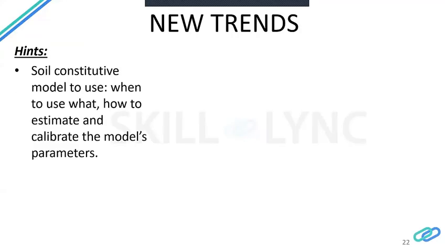Another aspect when dealing with finite element modeling is the soil constitutive model, what type of soil constitutive model to use in the finite element and how to use it and how to calibrate its parameters. These are crucial aspects you have to consider.